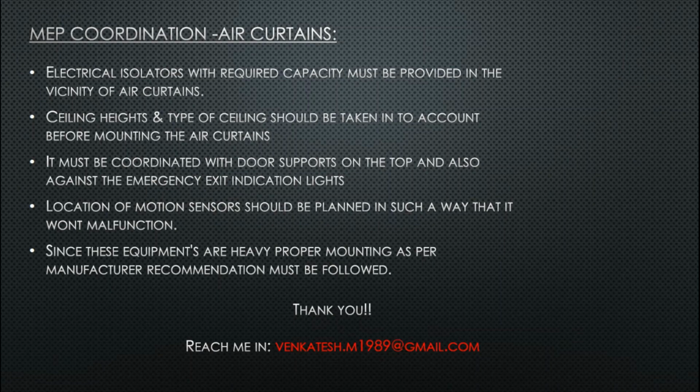Electrical isolators with the required capacity must be provided in the vicinity of air curtains. This enables maintenance, and whenever there is a stoppage of the air curtain, the access to the air curtain power will help the maintenance people to switch the air curtains on or off with convenience.